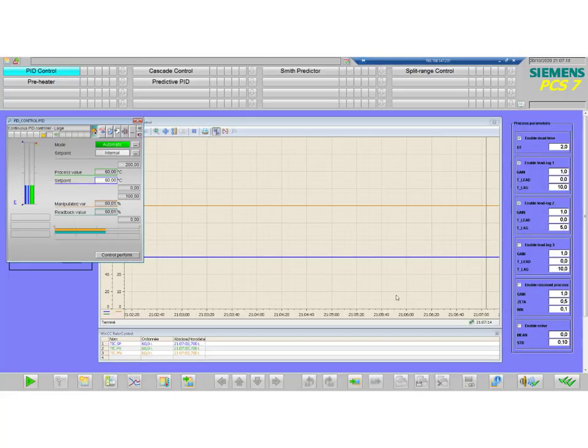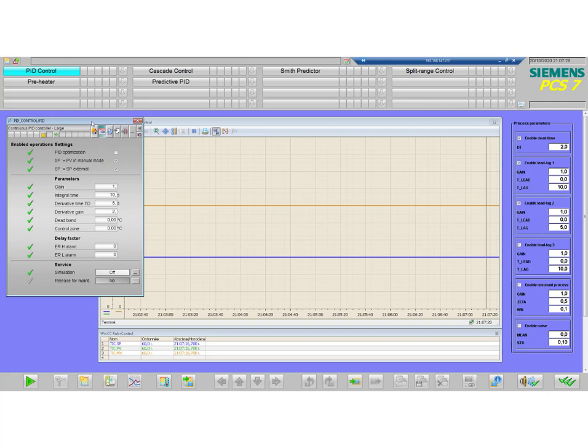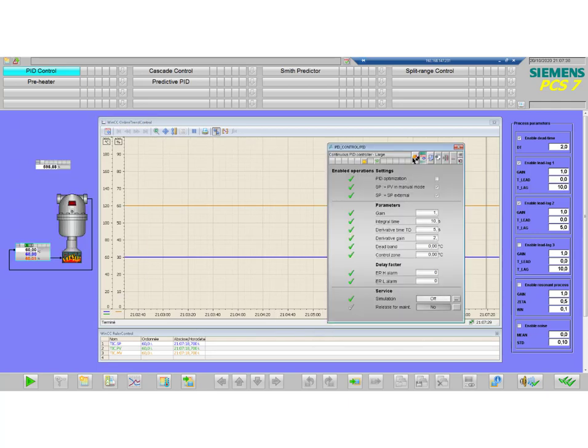Let us now come back to our process. It's 2 time constants, right? And at that time the other parts of the process are not enabled. So here we can have a look at the control parameters. Here they are. So we have a controller gain of 1. I've simply taken the gain of the process and taken the inverse, so that's 1. As an integral time constant, I've just taken the main time constant of the process, so 10 seconds.